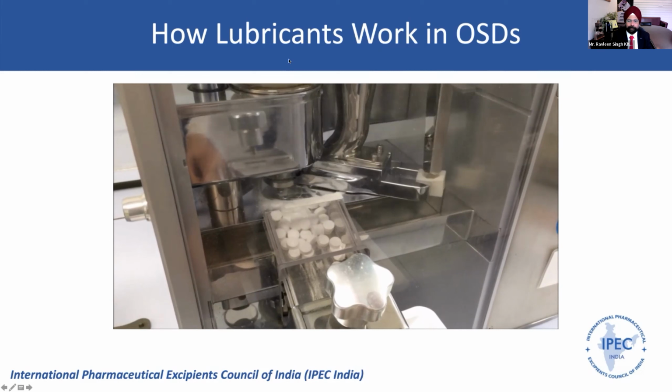So now, if we are talking in a normal seminar, I'll ask you guys to tell the difference. But here, I only have to speak for you. So the difference is that the tablets are moving very nicely when you have the lubricant in place. And in the second case, without the lubricant, the movement of tablets is very tough and tablets are not moving at all. They are stuck up there. So this is the role of lubricant in tableting. I hope this visual will give you insight how exactly the tableting goes on.